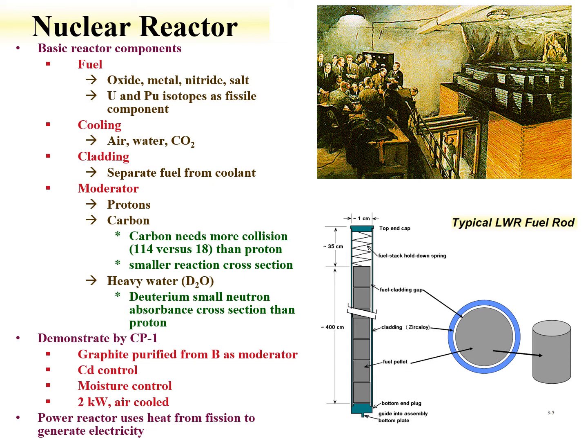And since this heat is produced, the reactors also need to be cooled. There are a number of different routes for cooling the reactor. They can include air, water, other gases such as carbon dioxide, helium, or even a liquid metal such as sodium. Most reactors have some sort of cladding material which separates the fuel from the coolant. An exception to this is molten salt reactors, in which the fuel itself is molten, and it's contained often in a large vessel.